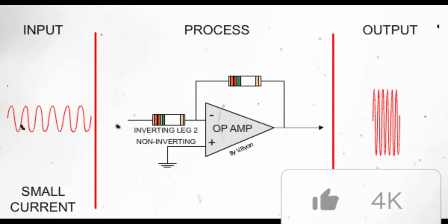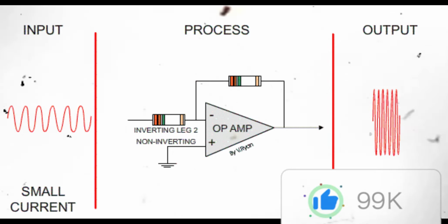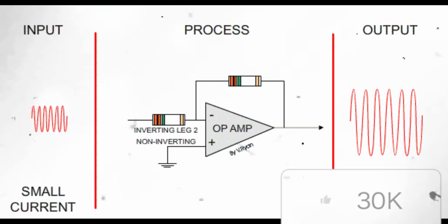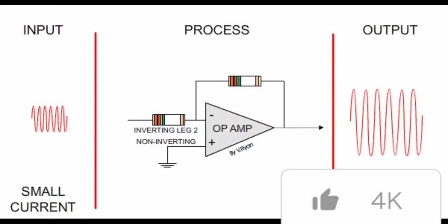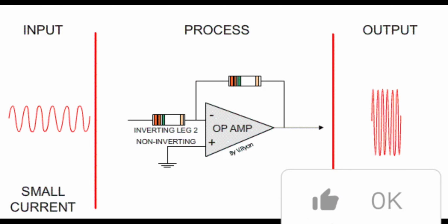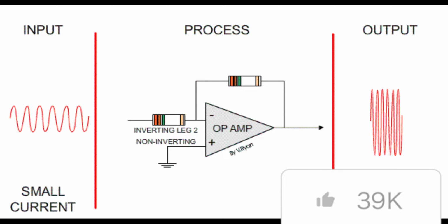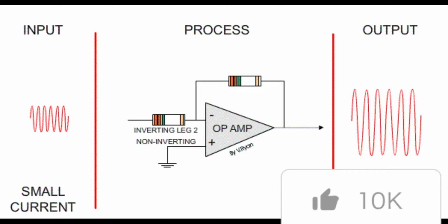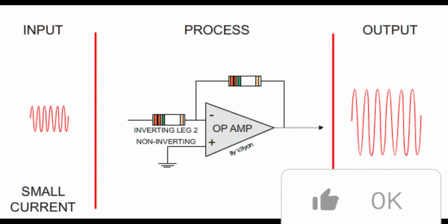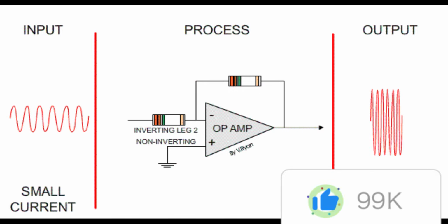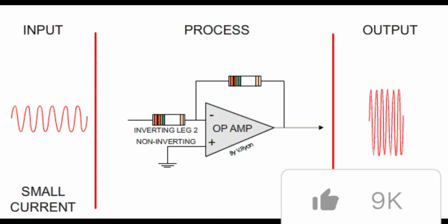Engineers should also be aware that slew rate values vary according to the type of op amp used. In actuality, the higher the slew rate, the faster the output can change. So, low-power op amps might yield a slew rate value of 1 volt per microsecond, while faster op amps can produce rates as high as 1000 volts per microsecond.